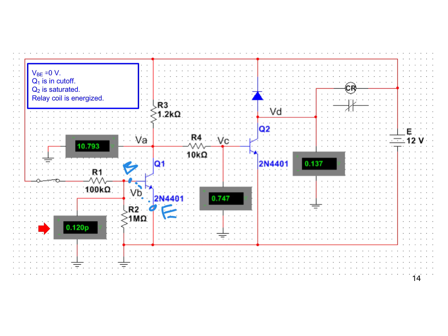But can we just call that, for all practical purposes, 0 volts? Because of that, it's pretty clear that the base to emitter is internally shorted. Then transistor Q1 obviously is not going to be working.